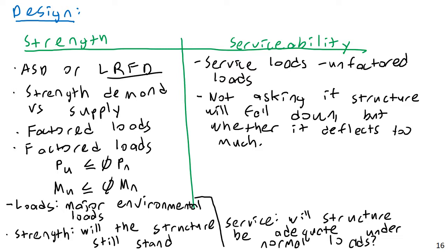So again, for buildings and structures, we don't want them to bend too much under normal everyday load. We don't want them to twist too much. We don't want them to stretch or compress too much. We want to limit our deflections, but only in terms of everyday loading. For major seismic events, for major hurricanes, serviceability is mostly about comfort, not about strength. So this is mainly a human comfort thing. This is about psychology, primarily, and also damage to certain materials, like drywall. Affects with an A, not an E. Affects human comfort.